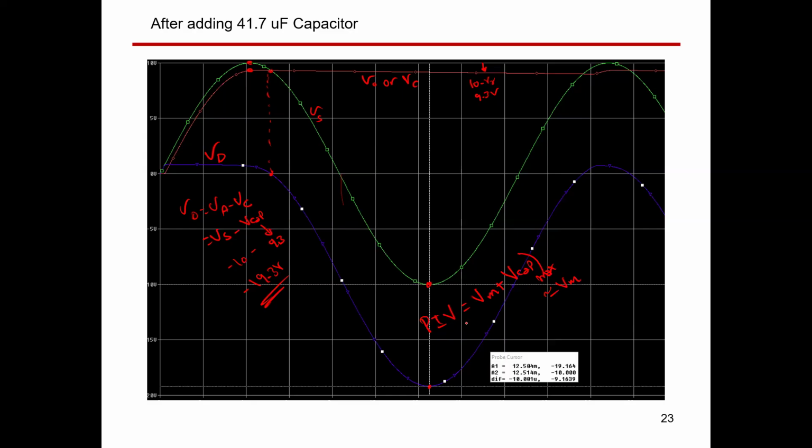Sorry, this is the diode peak inverse volt, not breakdown volt, okay? I'm not sure if I said breakdown or peak inverse. So the diode peak inverse volt is 2 V maximum. But when you specify a diode, you need to get a diode with a certain breakdown volt. So V breakdown, guys, has to be greater than peak inverse volt. And we should assume also a safety factor. So if I'm going to design such a circuit and I have 2 V maximum equals 20 volt now, I'm going to say get V breakdown approximately equals 1.5 times 2 V maximum.